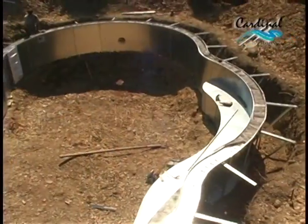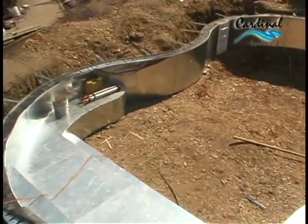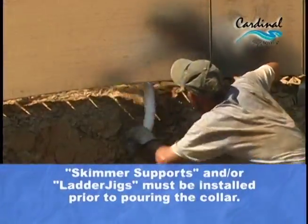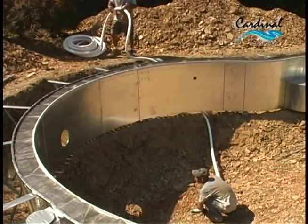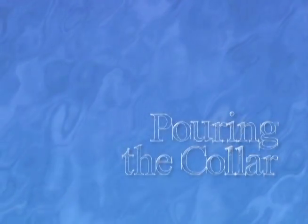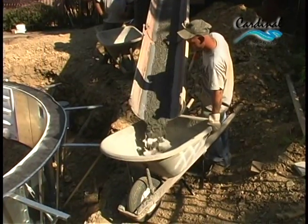With all supports and bracing in place and the wall system level and plumb, the last task before pouring the collar is to position the main drain. Run the main drain line under the panels and pull enough slack through to reach the center of the hopper. You're now ready to pour the collar.